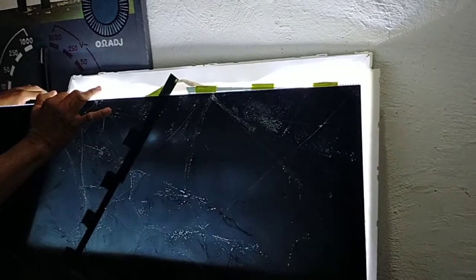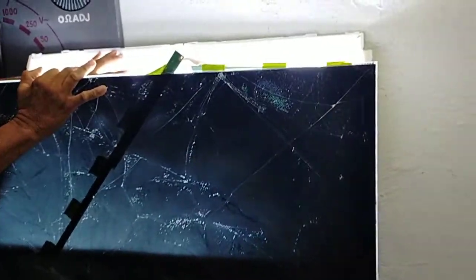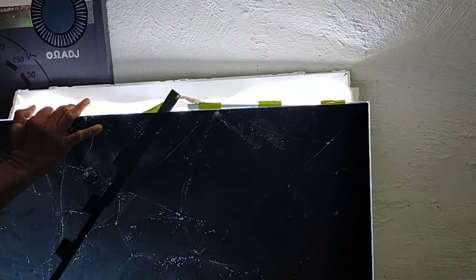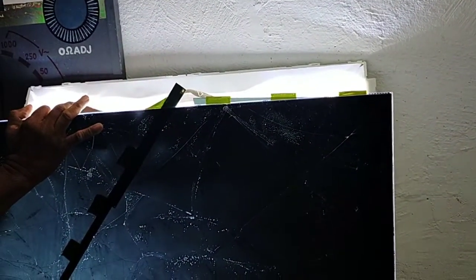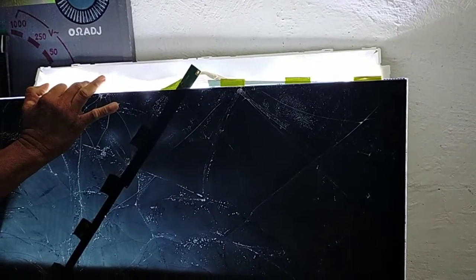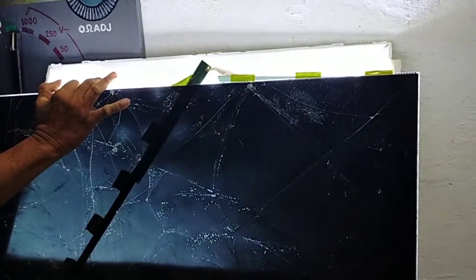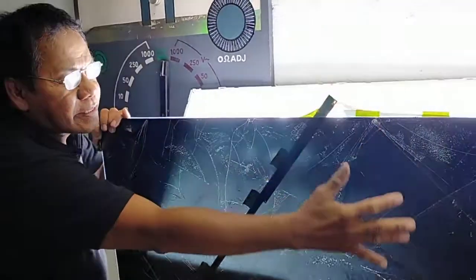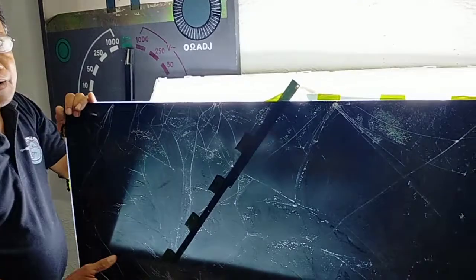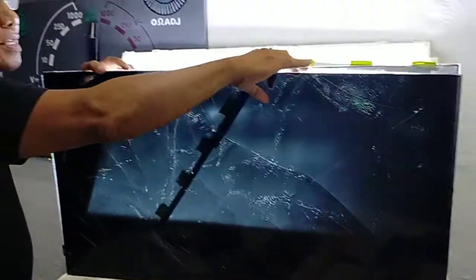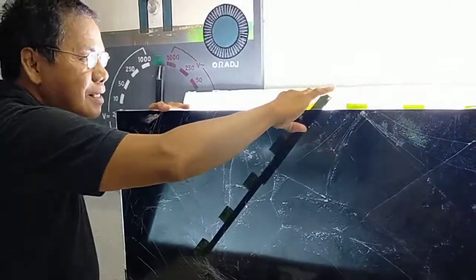The reflector, the diffuser sheet, the prism sheet, and the optical sheet are used to intensify and gather the light from the LED efficiently, in such a way that there is a very bright light displayed on the screen. The purpose of the light emitted by the light emitting diode is to activate the liquid crystal display here.